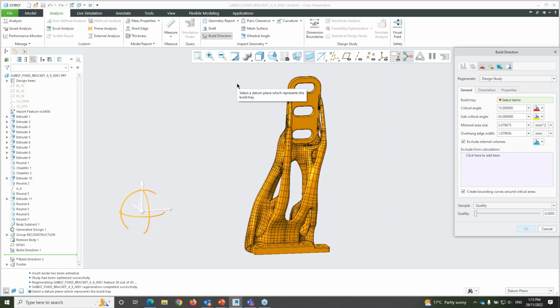If you're using a polymer, support material does not matter a lot, because support structures are printed in a low density format and can be easily removed by hand or washing later. But when it comes to metal printing and parts like this, it's very critical to consider the support material, because at the end of the day, it is a hardened piece of metal attached to a finished part, which you can only remove by post machining.